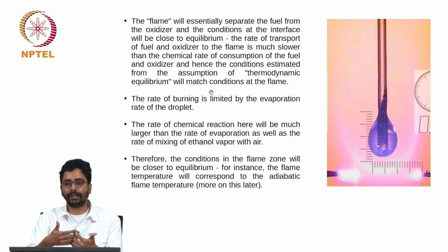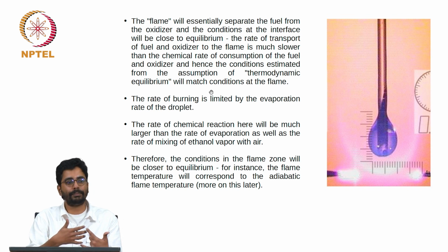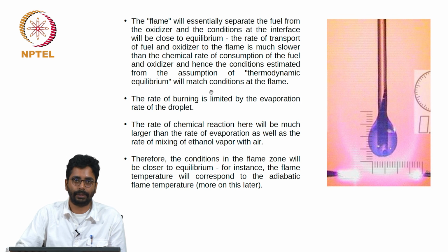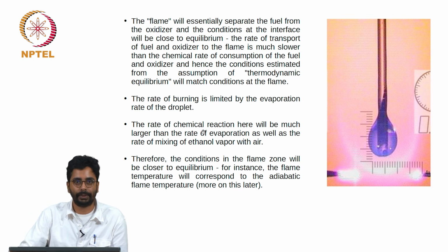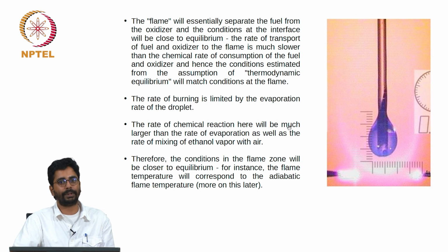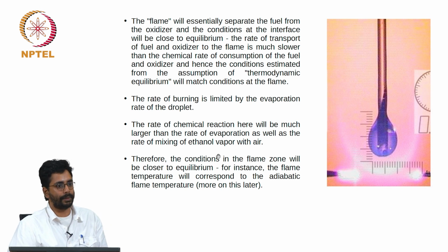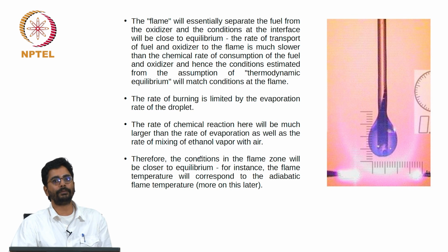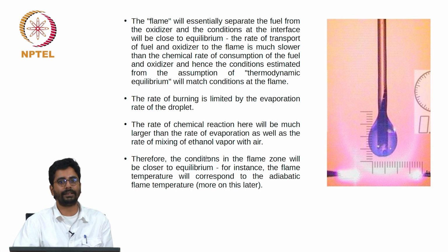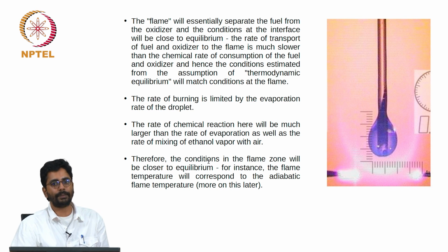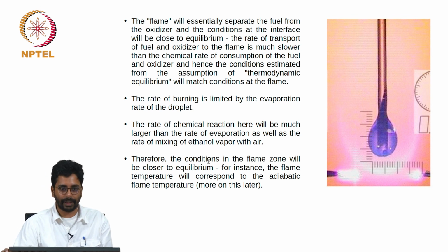What you need to accurately account for is the time it takes for the mixing of the reactants to happen, or mixing of the fuel with the oxidizer to happen. So, the rate of burning is limited by the evaporation rate of the droplet for the example that is shown here. The rate of chemical reaction here will be much larger than the rate of evaporation as well as the rate of mixing of ethanol vapor with air. Therefore, I am just repeating this point, the conditions in the flame zone will be closer to equilibrium. For instance, the flame temperature will correspond to the adiabatic flame temperature.